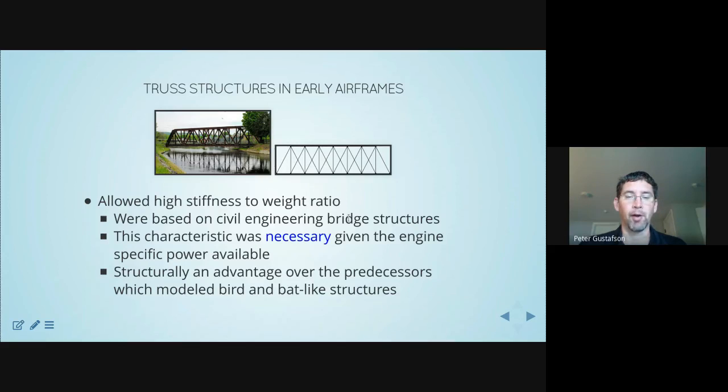As I mentioned in my prior discussion, the Wright brothers were using a canard. That's essentially they're using, instead of what we would now call a conventional tail, which is after the main wing, instead they had a canard, which sort of amounts to a tail in the front of the main wing. And one of the challenges associated with the Wright brothers aircraft, it was actually aerodynamically unstable, which made it quite difficult to fly. The other comment that was in the chat room, of course, that they were rectangular wings, and that was largely for simplicity of manufacturing.